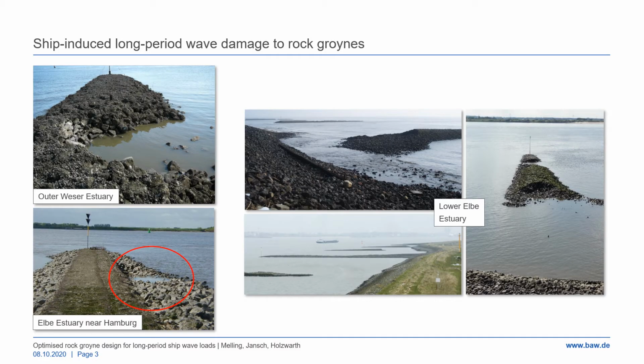Over the last 2 decades, shipborne loads have successively increased in response to increasing vessel dimensions. Ship-induced loads are now the relevant design parameter in large parts of German estuaries. Groynes and training walls in particular are vulnerable to the overflow processes witnessed in the previous video, since they have not been dimensioned to withstand these types of loads.